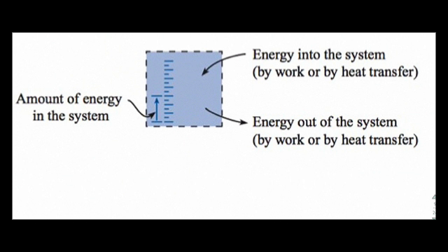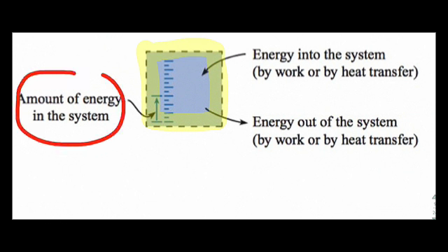The way I might answer this is, I'd draw a box and identify this as a closed system. And I would state that we can talk about the amount of energy inside this system. And energy is a property that characterizes how much work can be done by the system. In very simple terms, how much weight can we lift through a distance? And there's only 2 ways to change the energy in the system.